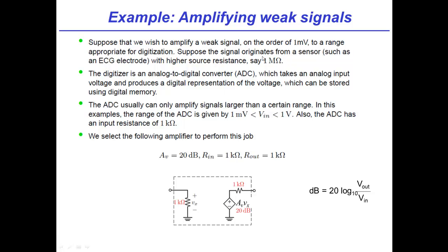So anyway, what we want to do is go from this sensor to something that is recording that voltage and then doing something with it. For example, it's taking the analog voltage, digitally encoding it, and storing it somewhere. Now the key though is I'm going to look for an analog digital converter from some box somewhere, and I find that that analog digital converter would really like to see voltages that are a bit higher than what this sensor can provide. And maybe, it's not specified here, but maybe the analog digital converter also needs a bit more current. It just can't deal with a source resistance that's high. That could also be the case.